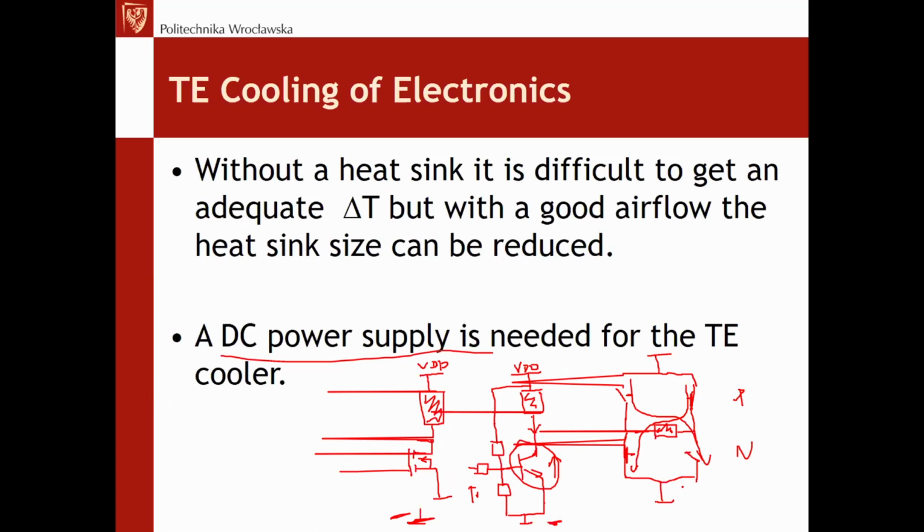So these are three major circuits for driving the Peltier. One very small practical remark. We don't have time to explain it in greater detail, but if you want to use this circuit in this place with the arrow, much better results are obtained when you put a strong coil here. So add some inductance.